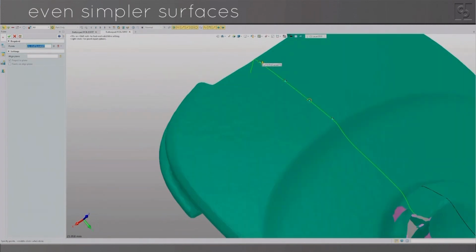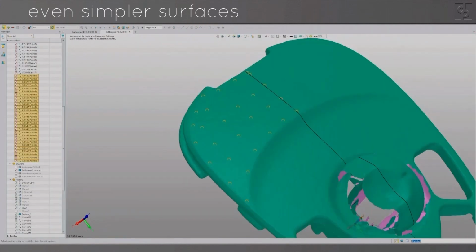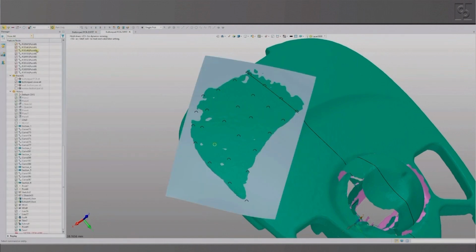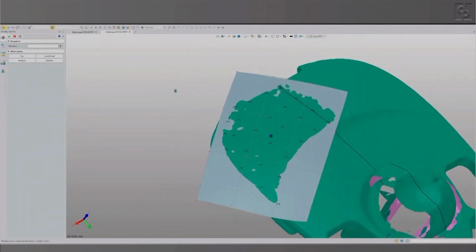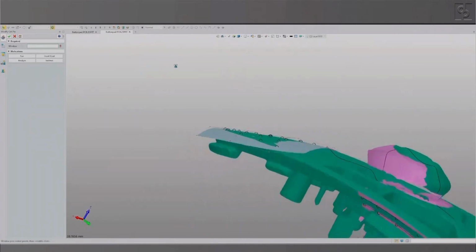So I'm drawing the points at 5 times normal speed, just on the patch that I want to apply the surface to, and then selecting those and choosing to wrap a surface with a U and V degree of 3, which is as low as you can get. And when we look at the control points on that surface, the number of them is very low, which is what we want for a simple surface.